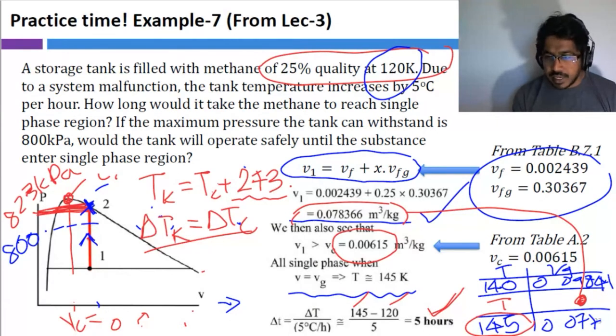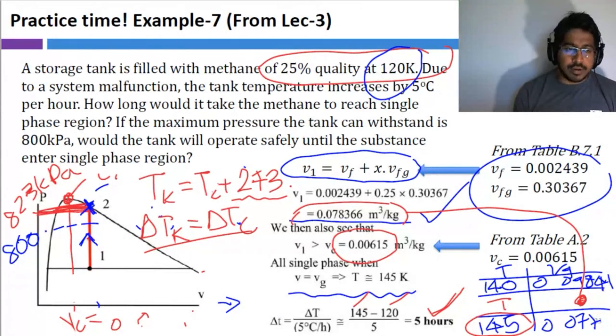So if we get this on the exam, will we always have a constant volume in the question? No, always constant is not a thing. If you solve the assignment questions, you'll see you have to look at the physical system. If it is a storage tank, it does not change the volume, right? If there's a piston cylinder mechanism, there's potential that it changes the volume. And obviously this question itself, I won't give it in the exam, right? Are we clear?